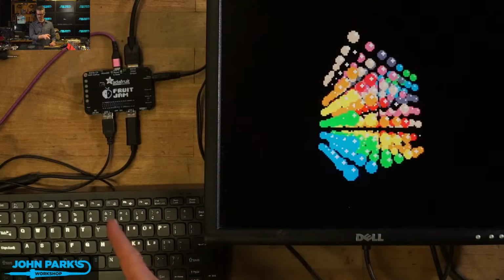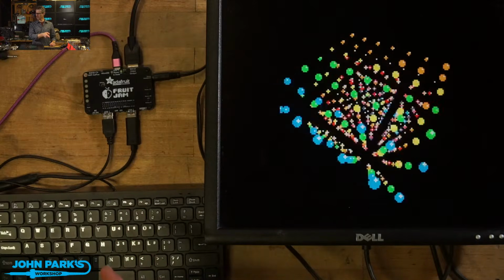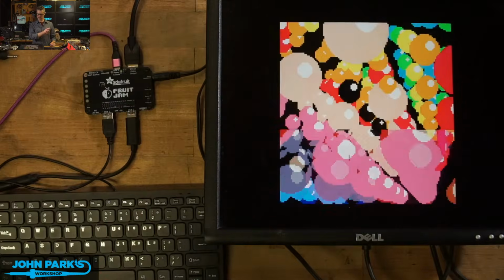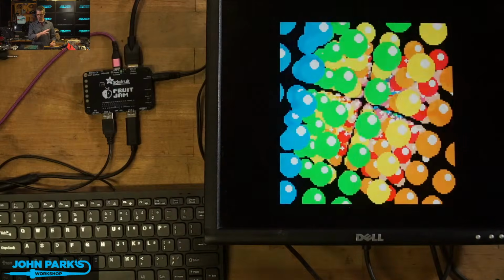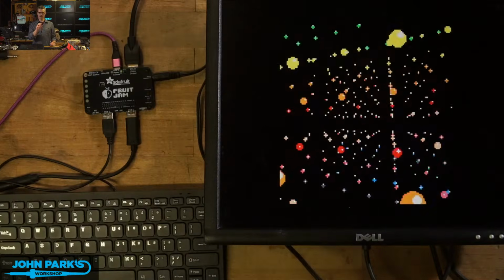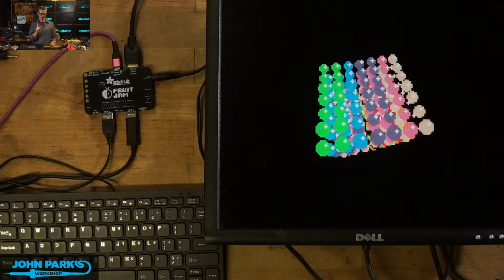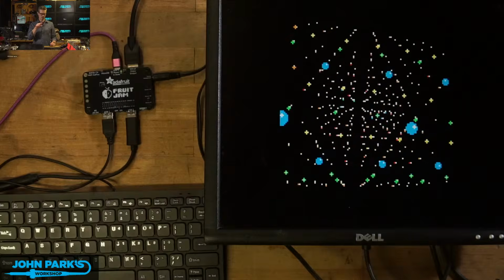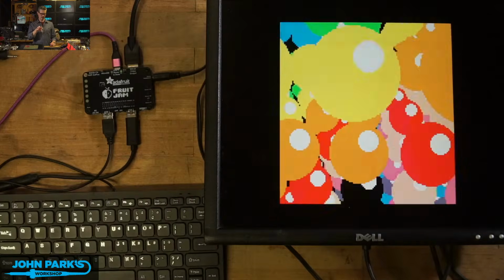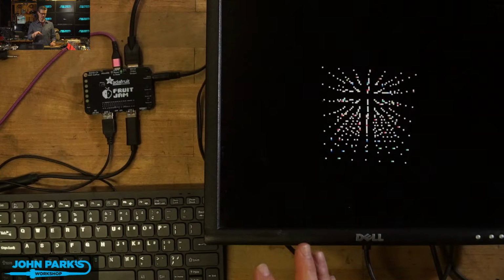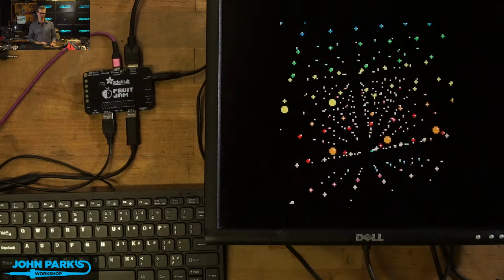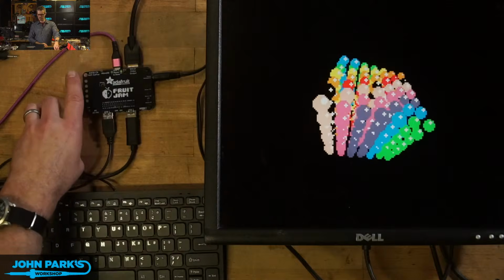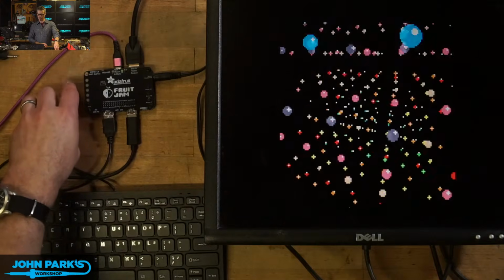In Fruit Jam Pico-8, the authors said it is pixel tripled. So 128 times 3. However, I believe when that frame buffer hits the DVI output circuitry on the PIO of the RP2350, it's actually sending out a 640 by 480.